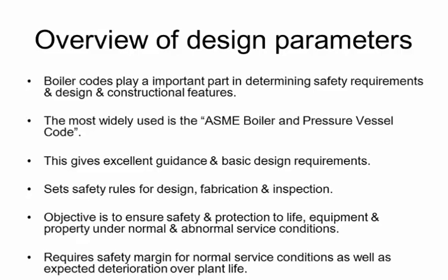This gives excellent guidance and basic design requirements, as I just mentioned previously. It sets safety rules for the design, fabrication, and inspection of boilers. The objective is to ensure safety and protection to life, equipment, and property under normal and abnormal service conditions. So it requires a safety margin for normal service conditions, as well as the expected deterioration over the plant life or over the design life of the vessel.